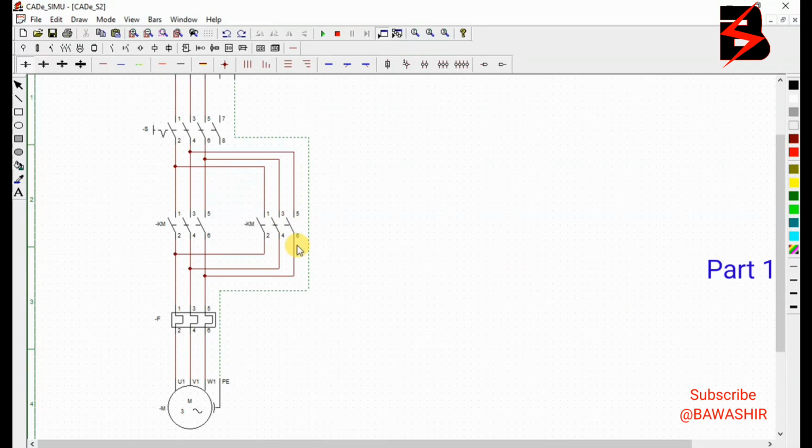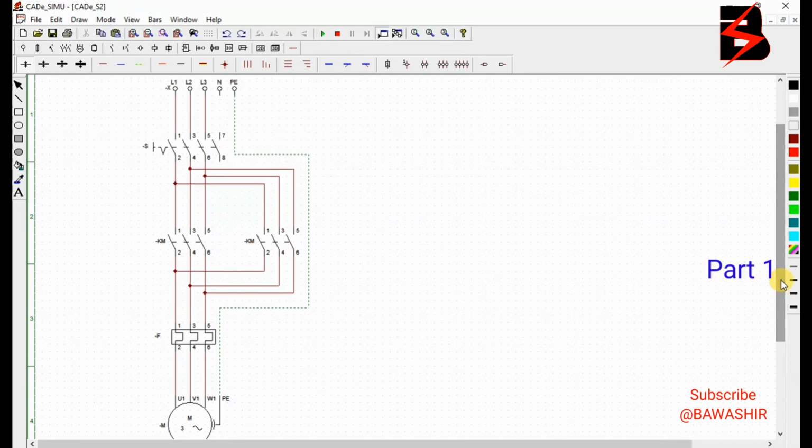So when we design our control circuit, make sure that when this contactor is on, this one is off. When this one is on, this one is off. That logic is called interlocking. Let us see as we design our control circuit how we come about with that. Since I've said we have 2 different control circuits, they look different, just because the starting switches are the ones which are different, but the circuit is one with a singular power supply.